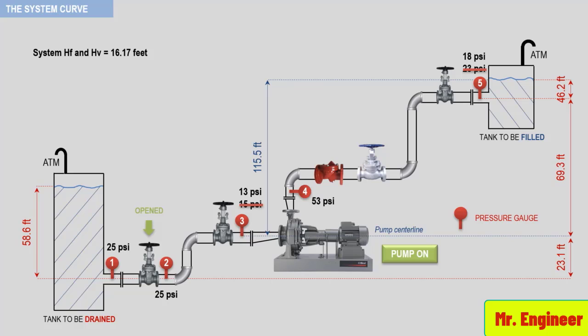For this reason, my advice to you, if you want to accurately determine the characteristics of your existing system, regardless of when it was built, is to install gauges on your pump and piping system. Teach the operators and maintenance personnel to interpret the information as we have done with this last example. The configuration on which we have applied the Backus and Custodio method that you can see here, although simple with one pump, is more or less representative of all systems. So it wouldn't be difficult for you to reproduce it on your existing system.